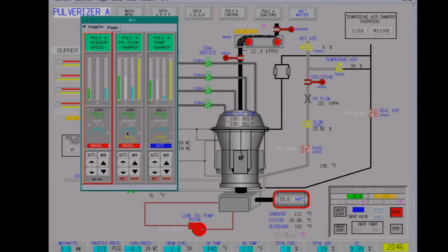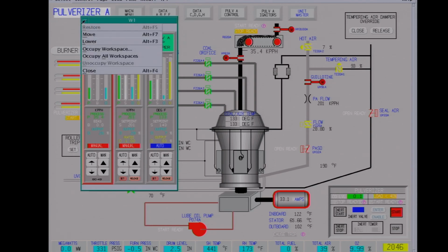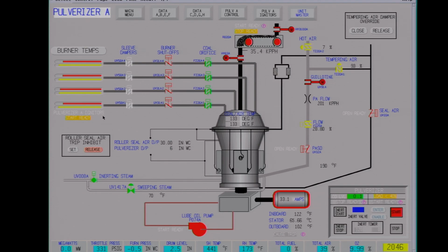There's an air-fuel ratio you have to maintain. On pulverizers, we're pretty high. As this temperature heats up, this is going to drop off. So usually you want like 180,000 pounds of air per hour per about 80,000 pounds of coal.